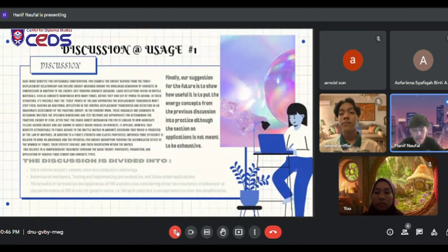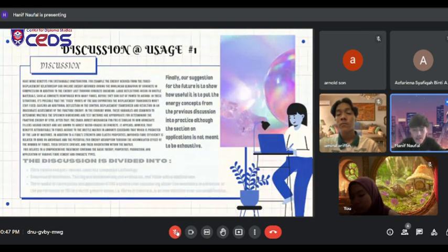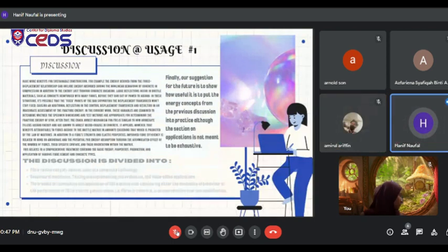In addition to fiber strength and elastic properties, improved fiber efficiency is related to bond anchorage and the potential for energy absorption due to the cumulative effect of the number of fibers, their specific surface and their orientation within the matrix.